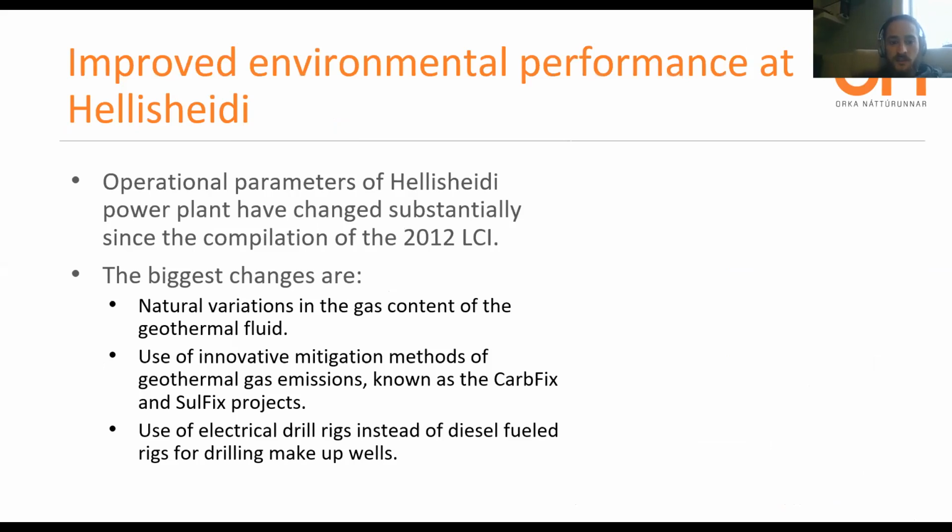And because of this work, there have been substantial changes to the operational parameters. For example, CarbFix has been implemented, which I would imagine many of you are familiar with. If not, this is the process in which, because geothermal still has emissions that come from the chemistry of the geothermal fluid, they have a capture plant that runs the CO2 through water and captures it in a liquid. Then they send it back down into the wells and into the geothermal reservoir, where that CO2 mixes with the porous rock that we have here in Iceland. Because of the chemistry, that CO2 will be solidified rather than being emitted into the atmosphere.